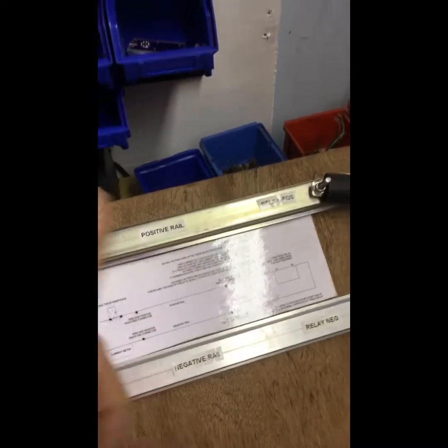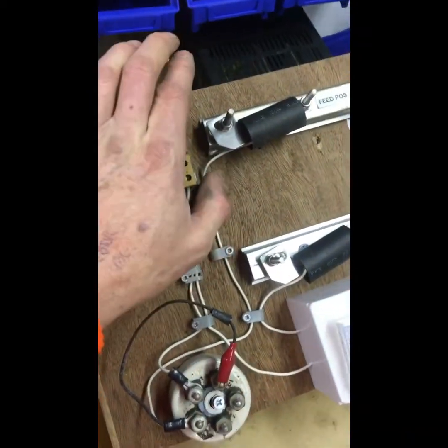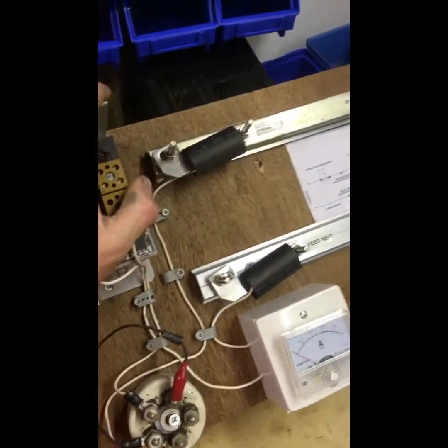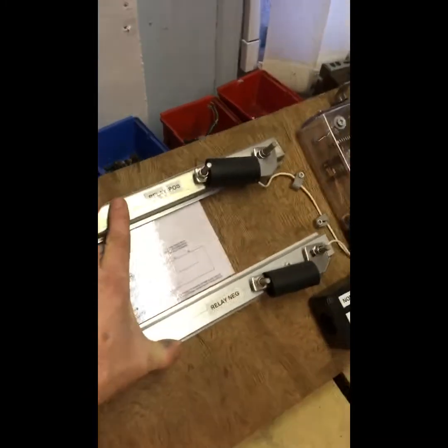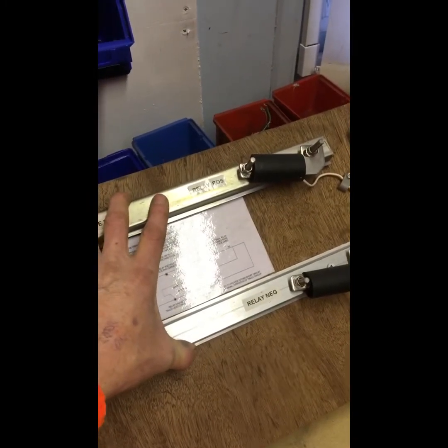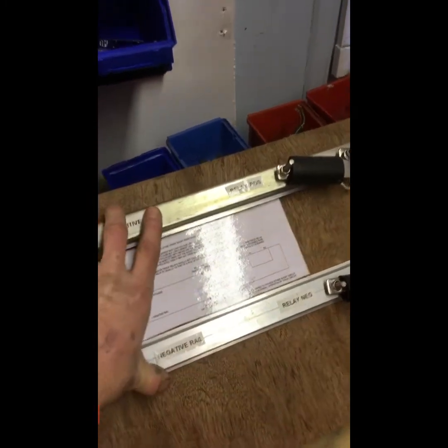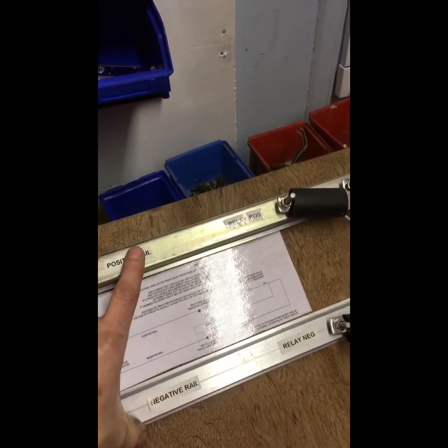As one of your tests on track circuits, you can remove the supply by pulling the fuses, and then with a meter on the track, see how the voltage drops down slowly over 2 minutes, because the ballast will have what's known as a battery effect, depending on what chemicals are in that ballast, the makeup of the ballast, where it is, local conditions. There are so many things. Some track circuits near factories, or heavily inundated with mud, will maintain a voltage, and that voltage could potentially hold the track relay up.